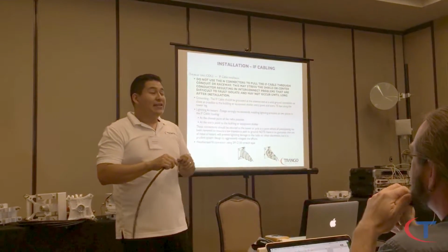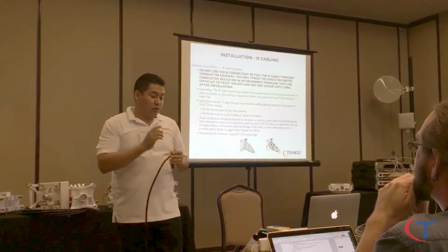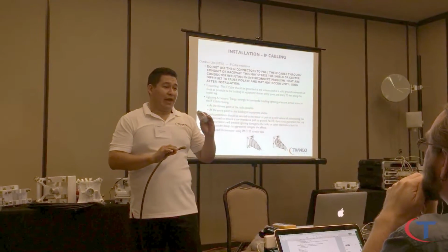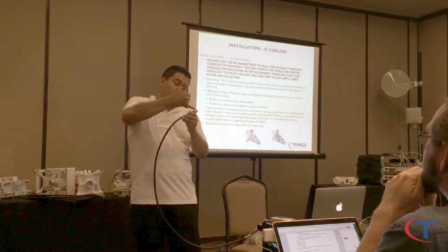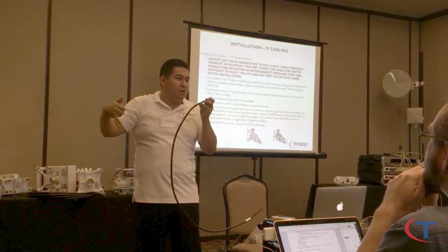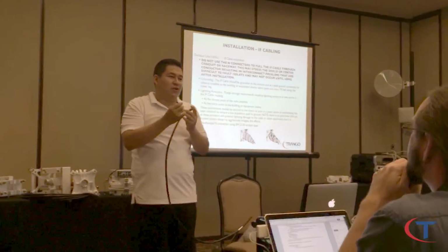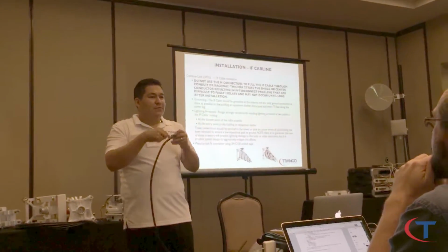And why do we want to do that? Just because of the cleanliness of the installation. When you put the actual sticky stuff on top, it's going to get really bad. So in case you have to cut off the connector and redo it, when you grab your knife and strip it apart, you're going to peel it off, and it's going to be at least clean enough that you won't get all sticky, okay? So you want to do one 3M tape.